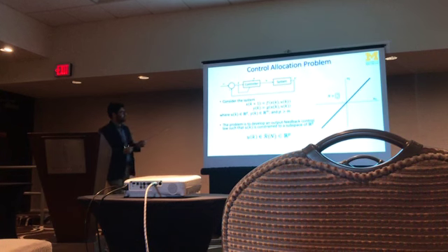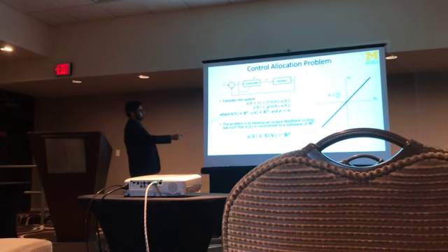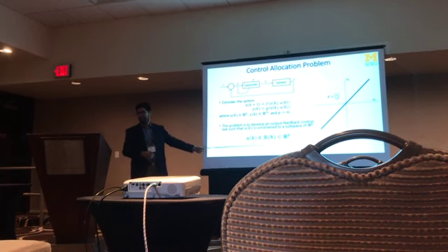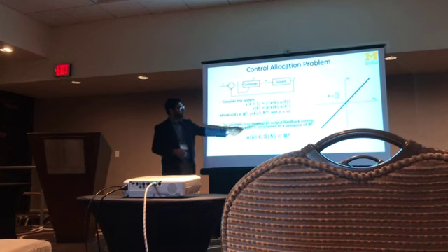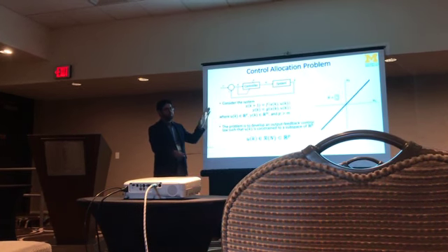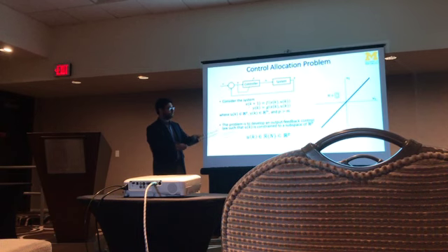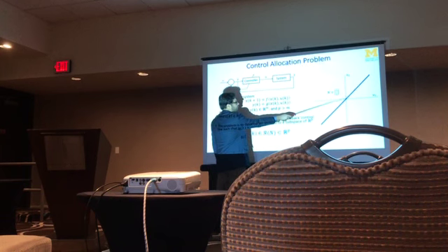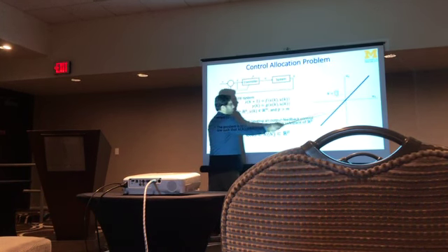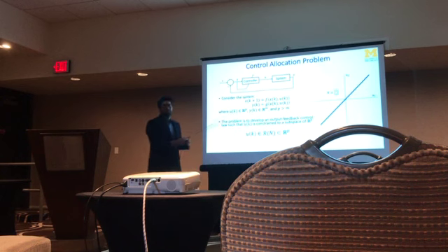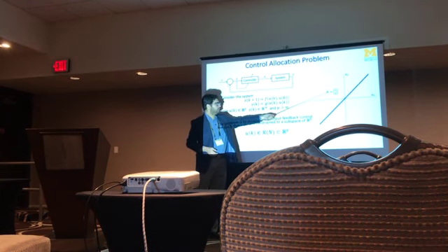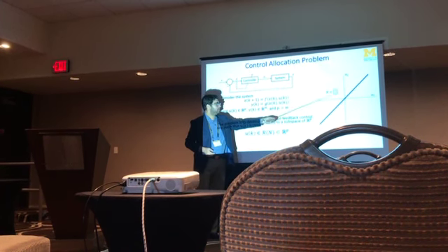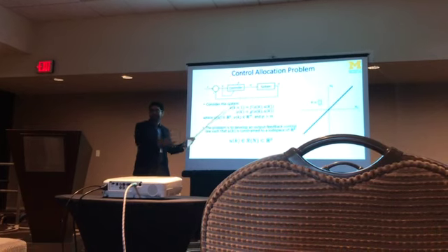The problem is to develop an output feedback control law for u of k, such that this input u is constrained in some subspace. For example, if you had two control actuators, you don't want them to just go anywhere, but you want to constrain these two actuation inputs to this subspace, then that's the problem. You choose the subspace defined by the matrix N as the range space of the matrix N, and then the control should stay inside that subspace.